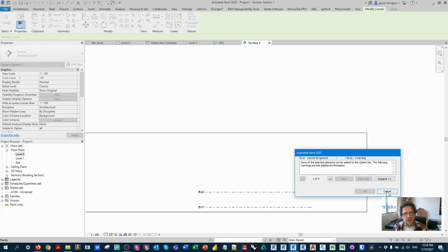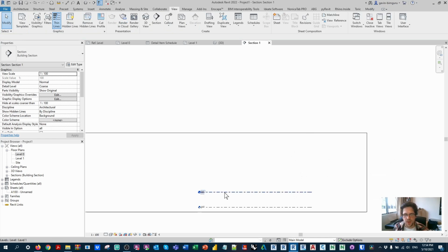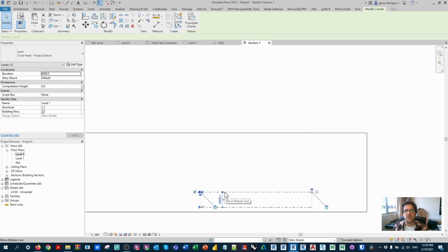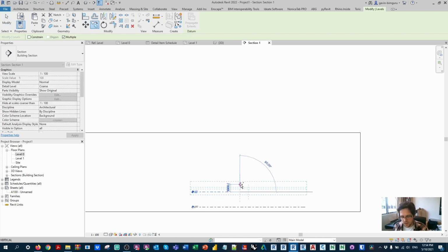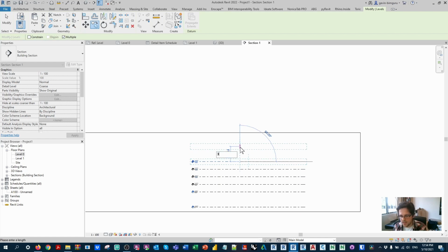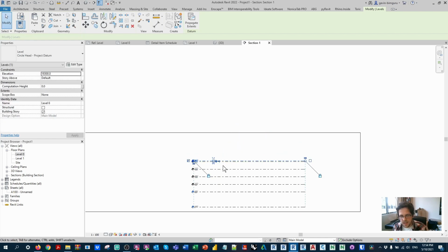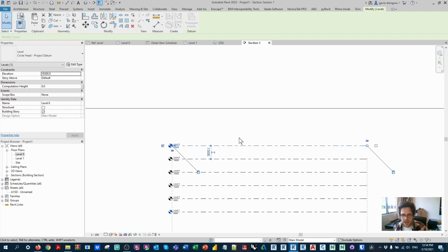We can move grids, but not levels. So in this case, you really do end up with quite a messy model once you're looking at different floor-to-floor variations. So I do usually err away from massing at some point. So in this case, I'll just add another floor just at 3 meters, and I'll just maybe make a few more. I could use the array tool. I guess that probably would have been a smarter idea. But for now, let's just do that many levels.